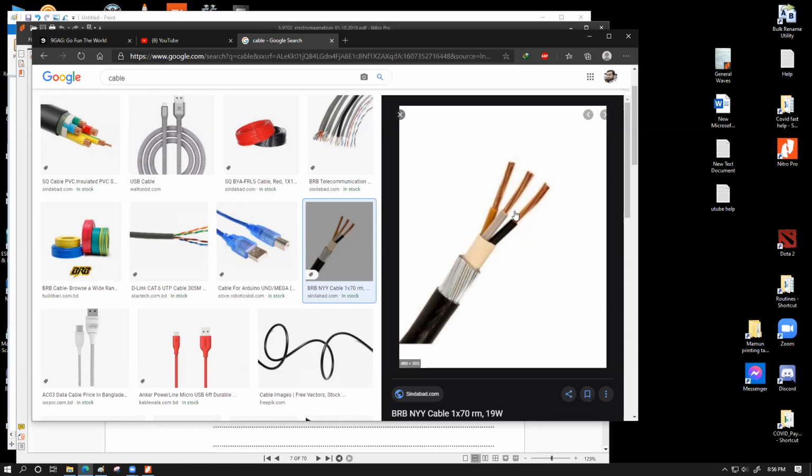And then try to think of a typical value of amperage that this cable would carry for regular use equipment. For low power equipment you can consider bulbs, and for high power usage you can consider an AC. I can help you in this aspect: think of a typical value for the power of these components and divide that by 220, the typical RMS voltage of our supply. If you divide the power by the voltage, you get the RMS current. So guess what could be the maximum current that you can get?